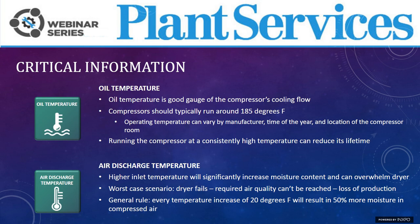Let's start with critical data. Temperature is certainly a critical value in a compressor system, and I'll start here with oil temperature. Oil temperature is a good indicator for compressor cooling flow. Running consistently at high temperature can reduce the lifetime of a unit.